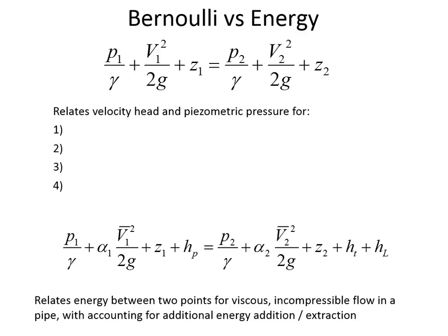And let me draw the typical shape of the velocity profile for laminar conditions. Okay, who can explain the bullet shape, what it's all about? Exactly. So where is the friction being applied? We all know that there's friction, that the pipe is pushing on the water. The pipe is pushing at the water where the pipe is. And the water that's furthest away from the edge of the pipe can flow the fastest. And so here we've got high velocity at the center, a little bit lower velocity as you get off the center line, and then at the edge of the pipe, the velocity is moving quite slow.